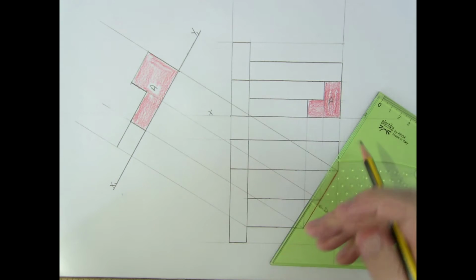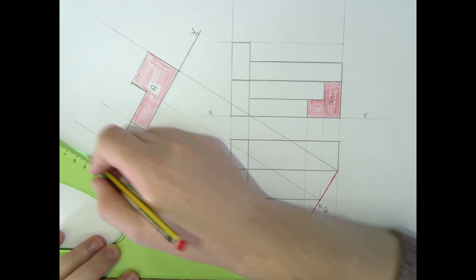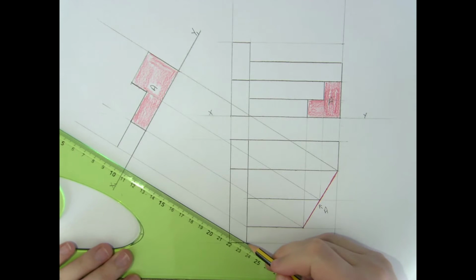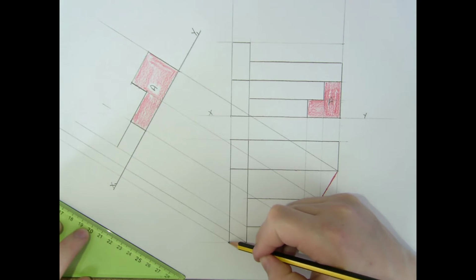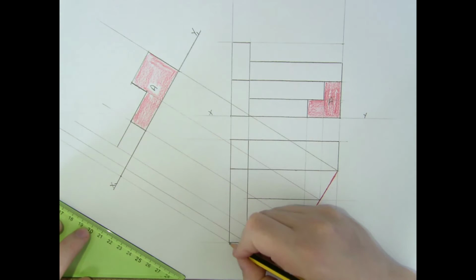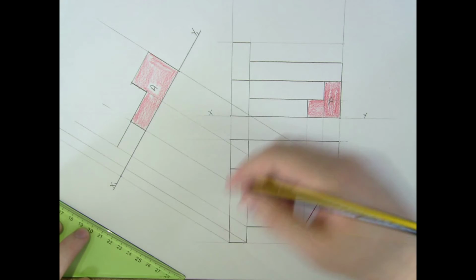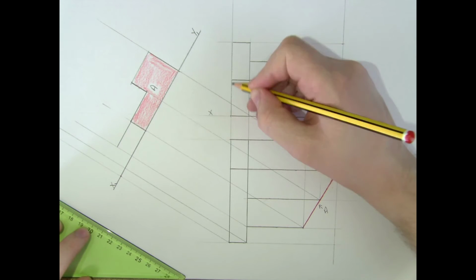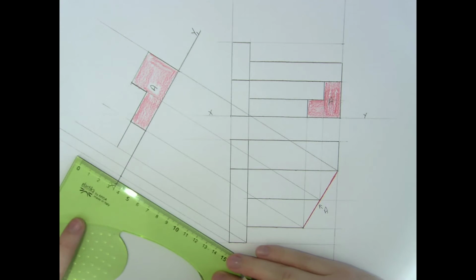Let's look at doing the wall next. So the front part of this wall, project it up. So each point is taken up at our 30 degrees. Let's find the heights for this point. It's going to be on the ground. So that's here. But also this point looking down on top of it is going to be this bit of the wall sticking up here at the front, which is up a height of 30. So I can mark up that height of 30.